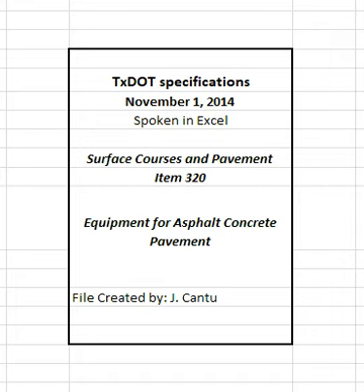2.1.1.6 Asphalt binder equipment. Supply equipment to heat binder to the required temperature. Equip the heating apparatus with a continuously recording thermometer located at the highest temperature point. Produce a 24HR chart of the recorded temperature. Place a device with automatic temperature compensation that accurately meters the binder in the line leading to the mixer.